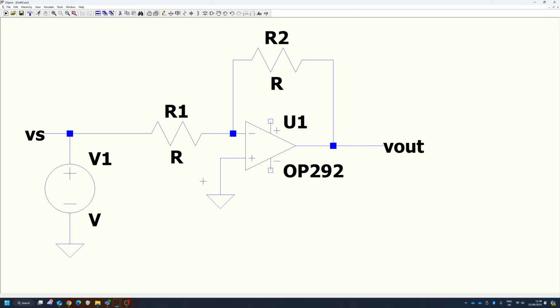However, real operational amplifiers need us to provide them the energy they will use to amplify the signal. That comes onto those two rails here, where one takes a positive voltage and one takes a negative voltage. And how do I generate a negative voltage? It is very simple. All you need are two voltage suppliers like this. I will bring one here, and another one I'm going to connect underneath. You see here I have a plus and a minus, a plus and a minus. So if I connect this one here to ground, as we always had,